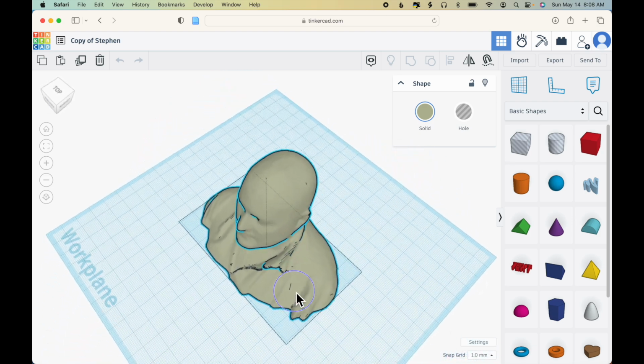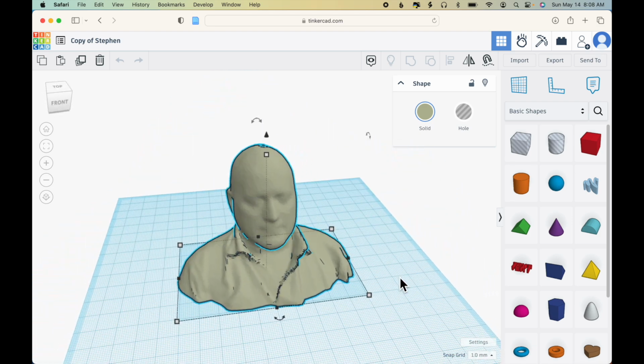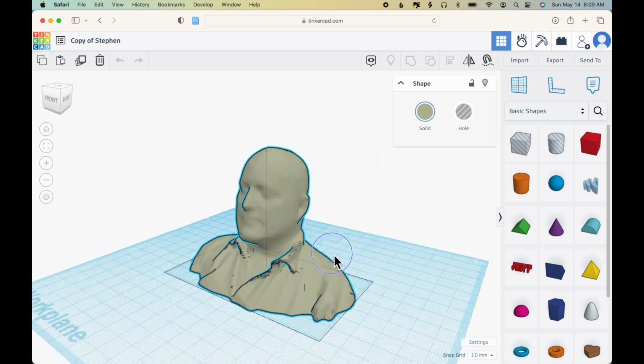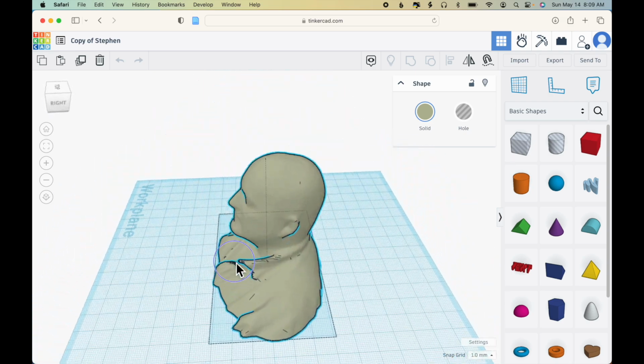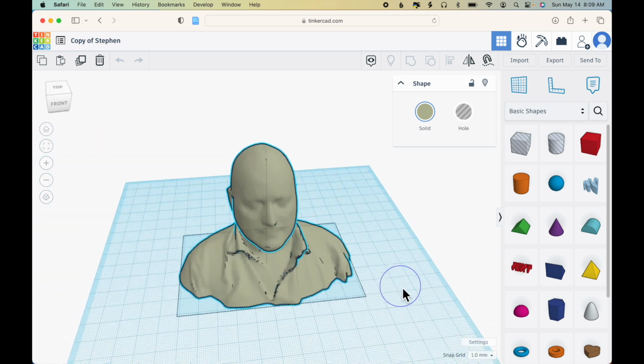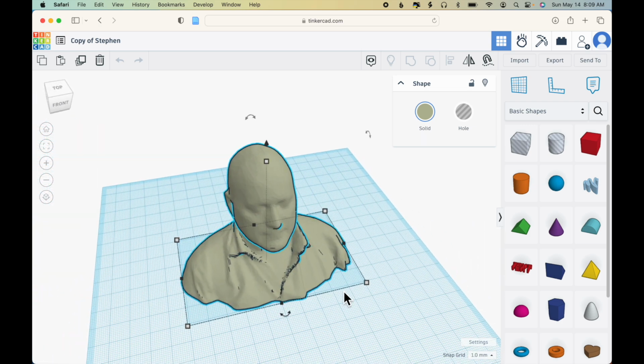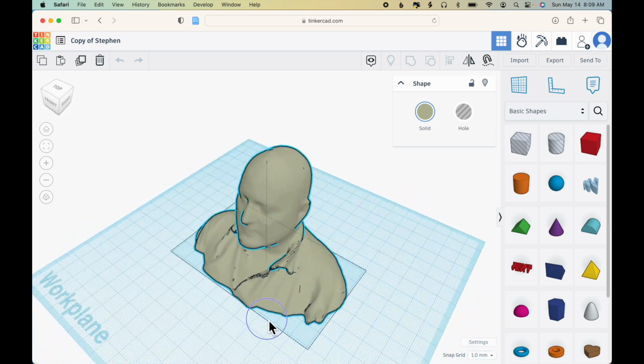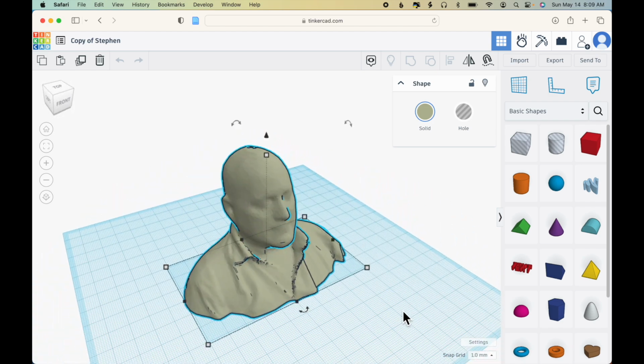Now, to rotate around the model, as I'm doing here, on my keyboard, I'm holding down the Control key and then tapping and holding on my touchpad of my laptop computer so I can easily scroll around. You're going to want to master this technique because you're working in 3 dimensions and you're going to frequently need to rotate around your model to see what it looks like.